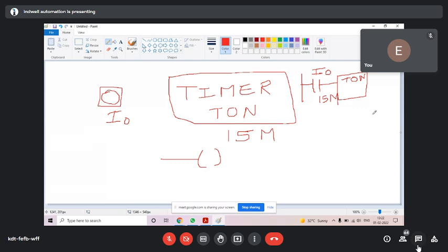The output which we have given in that ladder, specific ladder. What is the output in this ladder? We have just one timer in this ladder. There is no output, correct? Okay. So this is the problem. This is the practical problem. If you have this question where you have to run one on delay timer from a push button, you cannot run it.